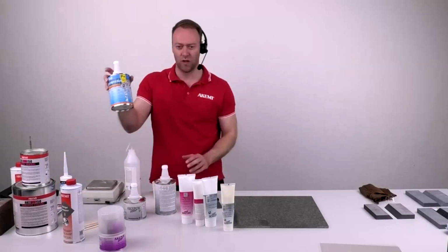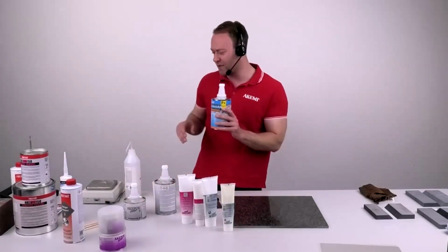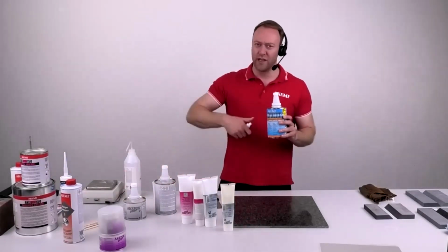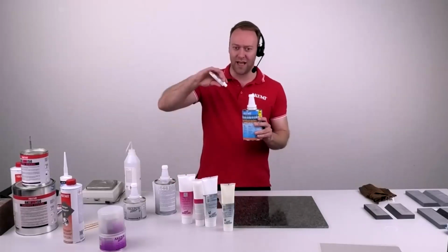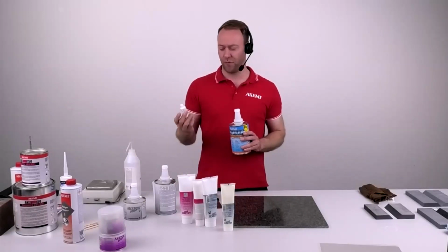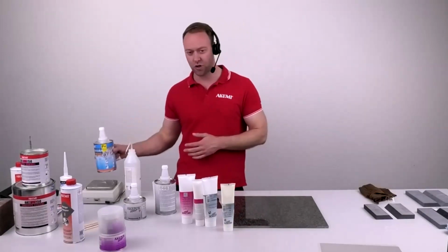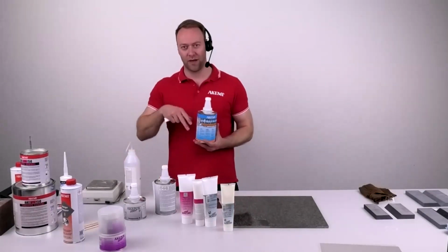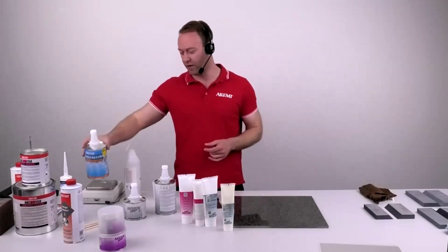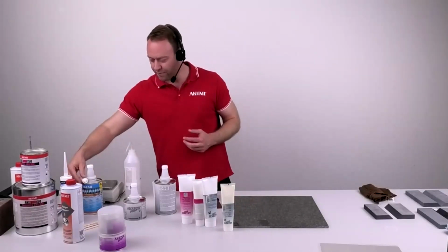When it comes to epoxy acrylates or polyesters with the hardener, usually the workers after a while know what 1-2% of hardener looks like. So in the beginning, if you're not skilled, also use a scale, but later on, usually they can do it by eye.